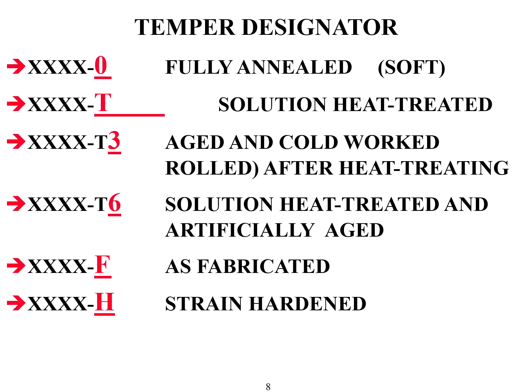T3 is a common heat treatment. As a matter of fact, 2024 T3 aluminum is the most commonly used structural aluminum. And in some cases, especially if you're working with extrusions, pieces that come in with shape, they will be in the T6 condition. So O, fully annealed. The letter T indicates it's had heat treatment. Numbers following the letter T define what type of heat treatment.